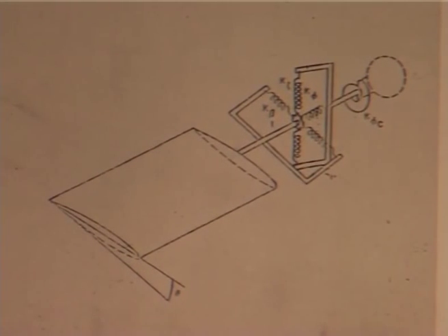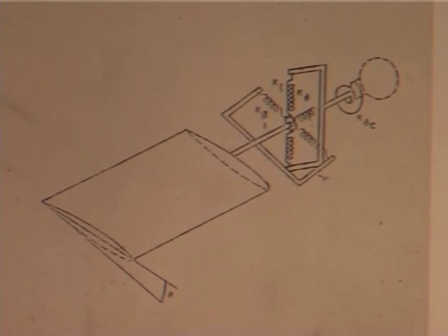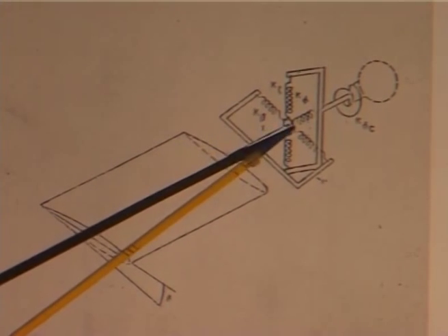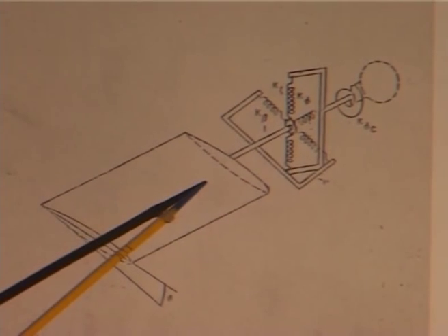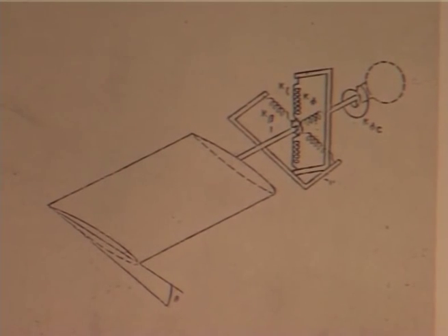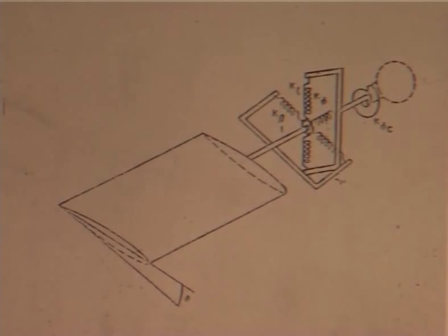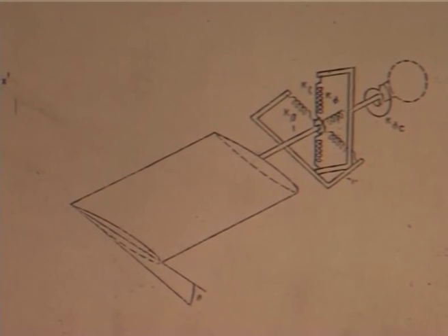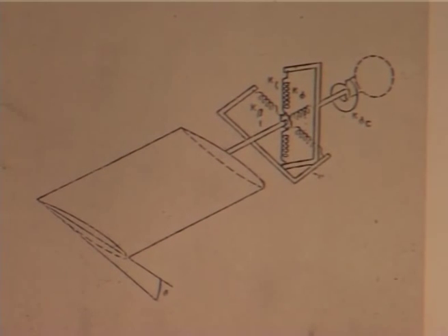Now, whether your pitch angle, whatever the pilot gives, does he give inboard of this or outboard of this? Okay. If he changes the pitch angle outboard of that, that means the spring assembly is not rotating, because this is lag spring, this is flap spring.